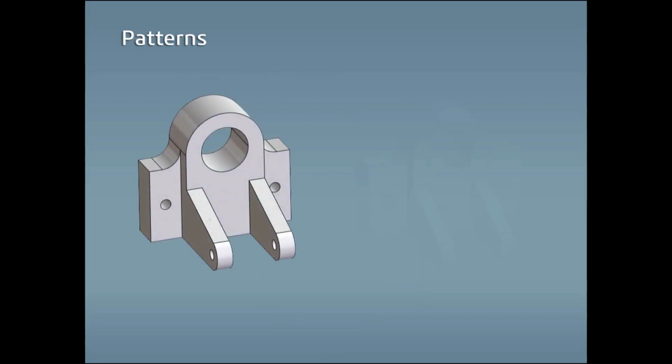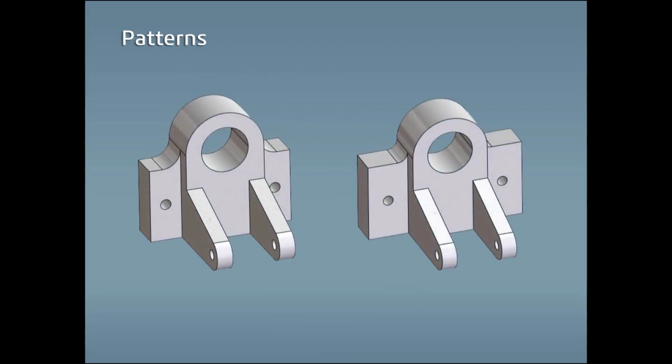One of the biggest advantages of creating these patterns is that updating the original instance will cause all the replicated instances to update as well. This makes it simple to make an adjustment to a single feature in the model, which updates the entire design.